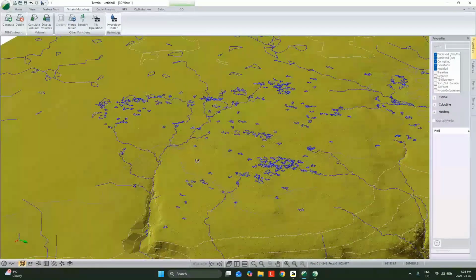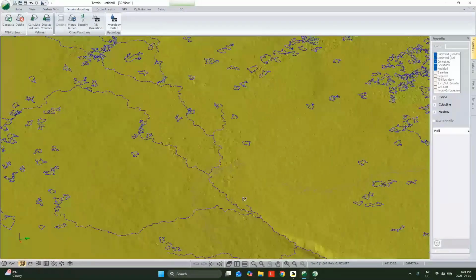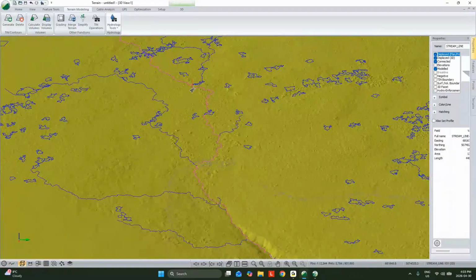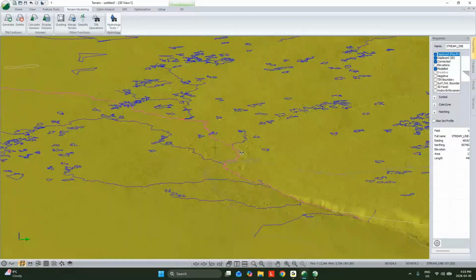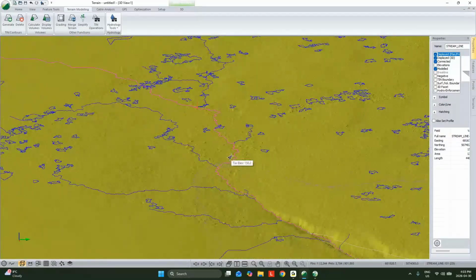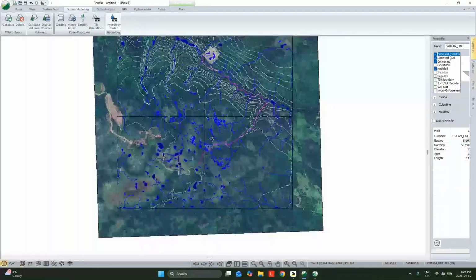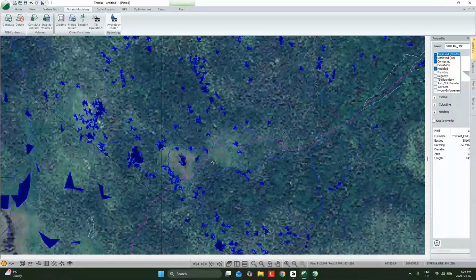Now, the other side of it could be that, and it's going to be more common in areas without defined channels and maybe poor surface quality data. So up here, I think we're kind of dealing with a swamp. And maybe it's a brushy swamp. Maybe the stream doesn't actually run through there. Maybe we've taken the time to GPS it, in which case we just bring in the GPS line and swap it out. But if it was just a field observation where I was there and said, well, actually it doesn't go from here all the way over to there, it kind of runs directly straight through, well, we could just edit the line.